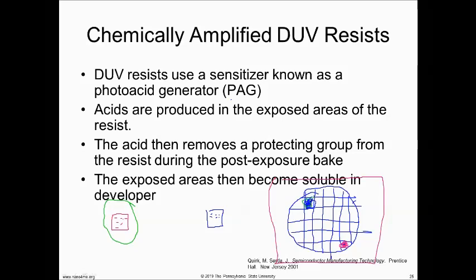And I'm going to do this one just one at a time, and it's going to be perfect, because I'm going to have perfect alignment. I can't have that if I do the complete wafer due to this moment arm or mechanical thing where I'm going to lose tolerance. Then I'm going to go to the next die, and I'm going to do this one perfectly.